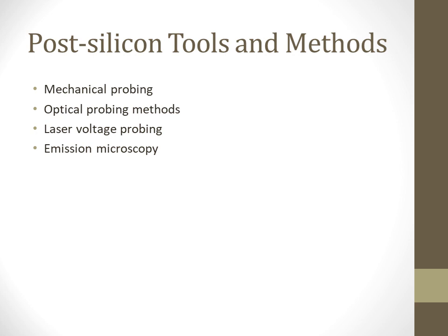As a result, more sophisticated optical probing methods have become the standard for evaluating signals. This allows the backside of the device to be probed after appropriate processing using optical methods. This method takes advantage of the fact that silicon is transparent to infrared light, and they are either active or passive.